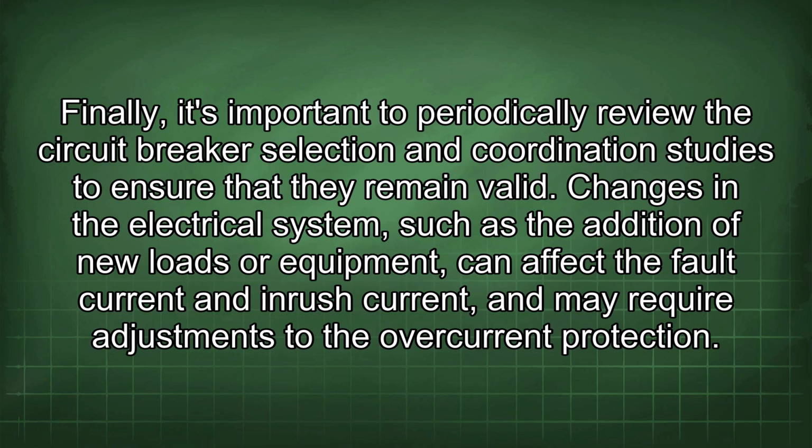Finally, it's important to periodically review the circuit breaker selection and coordination studies to ensure that they remain valid. Changes in the electrical system, such as the addition of new loads or equipment, can affect the fault current and inrush current, and may require adjustments to the overcurrent protection.